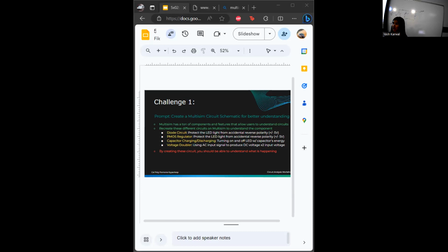Yes? So the positive is on the voltage below, not above? Yeah, because right now we're at the negative side. Just pretend that's not there yet. Okay. So when it goes in here, right now it's at 5 volts, right? And it goes through here. What should it be at? 4.3 volts at this node right here, right?